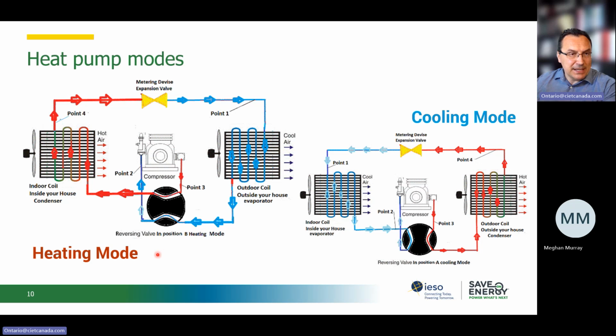And that's what the heat pump does by using a reversing valve, which changes the function of the 2 heat exchangers. So now the indoor coil becomes the condensing unit. It's going to reject heat into the air space, air that we want to heat, by absorbing that heat in the evaporator. That's now the outdoor coil.